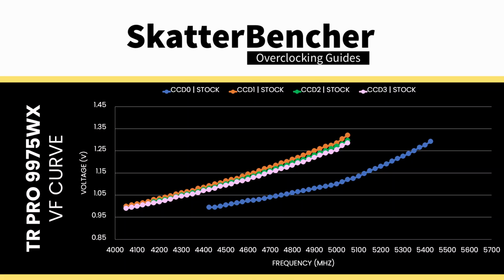We can immediately make a simple but obvious observation. The higher the frequency, the higher the voltage. For example, CCD 0 requires only 1.1 volt for 5 GHz. However, we need 1.25 volt for 5350 MHz. This also applies to the other CCDs. For example, on CCD 1, 1.1 volt gets us 4450 MHz, whereas we need 1.3 volt for 5025 MHz.